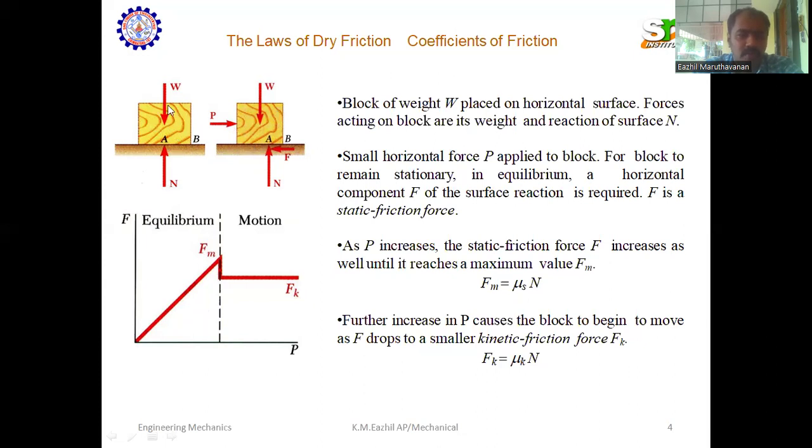If we want to draw the free body diagram for this particular block, the self weight of the block acts perpendicular to the ground plane. Then the reaction force acts perpendicular to the lying plane. This is the self weight. The block is in static condition. There is no frictional force acting in the first image.